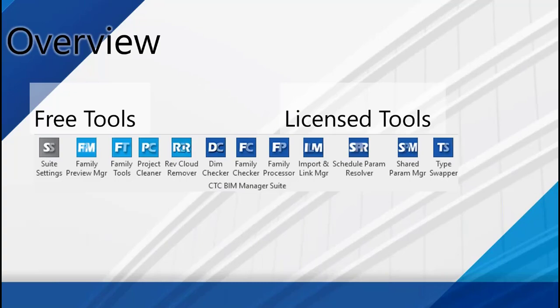Family Processor is next, and this is a huge tool that is really, really good at helping you manage and modify your family library. Whether it's to add a parameter to all your families, like maybe you want to put a version parameter in your family so that internally you've got version tracking now,